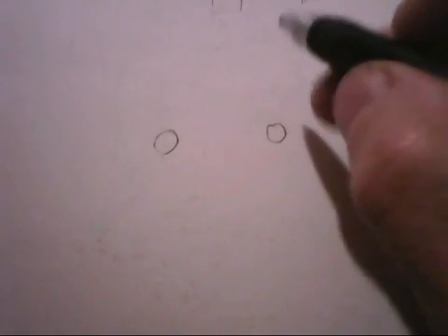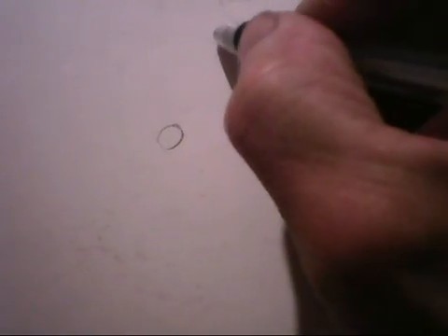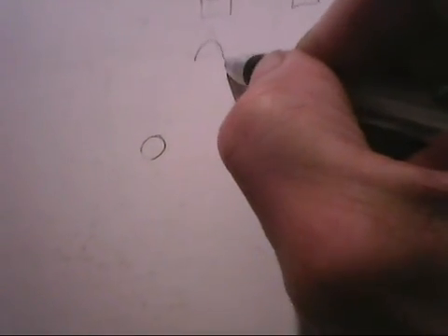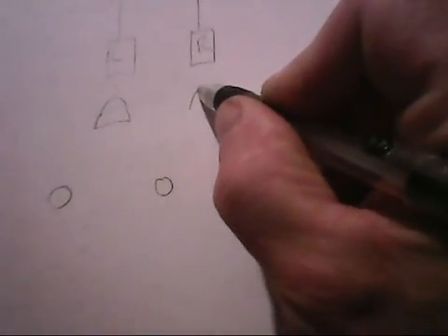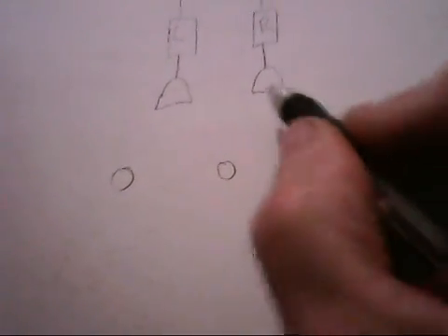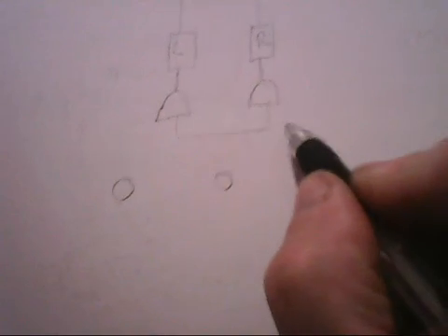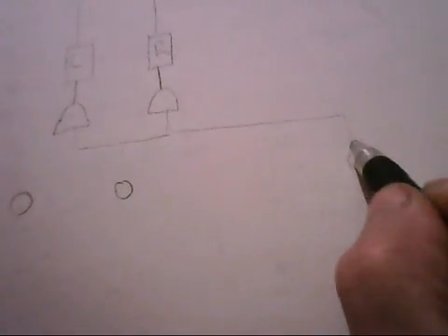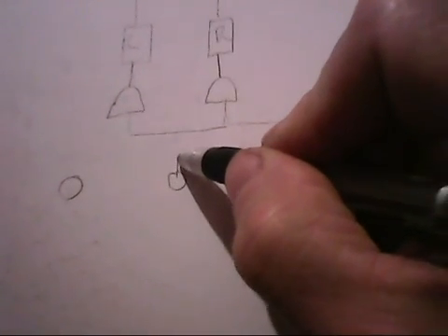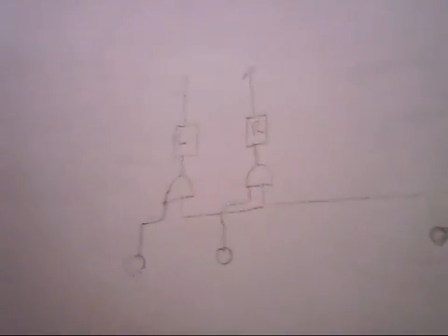So let's think this through here. If we had an AND gate, for starters, if we put an AND gate here and an AND gate here, with outputs going into the columns, and we tied one input of one AND gate to the input of the next AND gate, and then took that to a common firing button, and then took this input switch and this input switch, that would take care of that at that point.